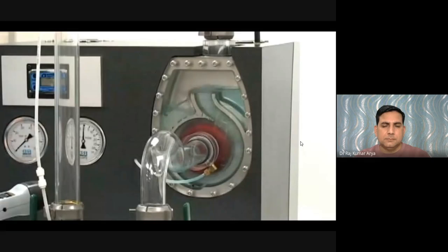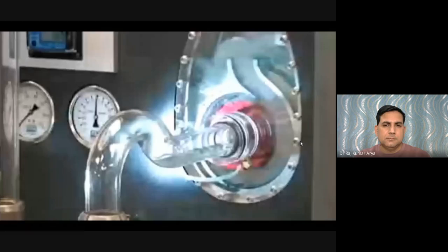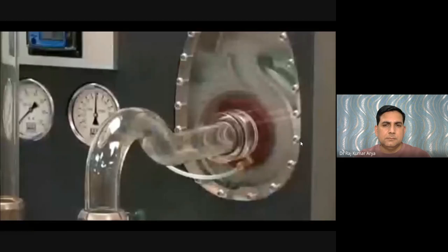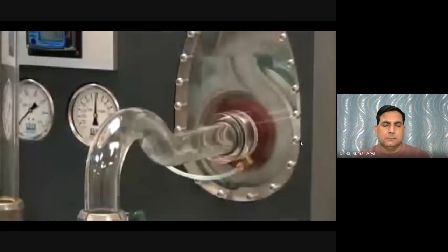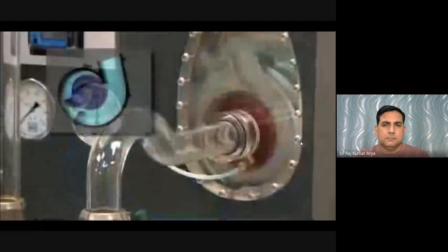After we fill the volute casing with water and we energize the pump, the impeller turns in a counterclockwise rotation. The initial prime of the pump is slung through the volute scroll, or the ever-increasing water channel, into a pressure cavity or a discharge chamber inside the volute. Inside this discharge chamber, the air and water separate.